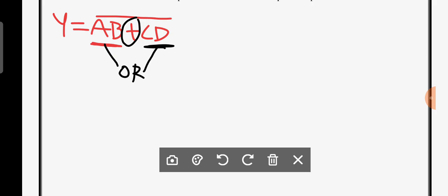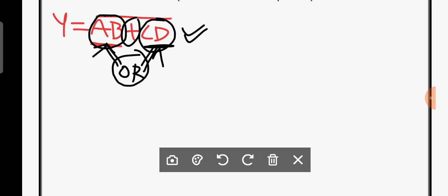These two are AND operations, but they are going to have an OR operation between them. Okay, therefore the small trick to design a CMOS stick diagram for such a complex Boolean expression is to maintain the continuity when you have the same type of operation. That means for AB, maintain the continuity, and for CD also. But when you do the OR operation of both, then discontinue the two expressions, AB and CD, and then perform the entire Boolean expression. Is it clear, all of you? Then once again, observe very carefully. Y equals (AB + CD) whole complement.